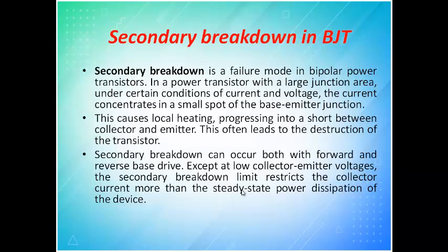That is what you have to remember. When you take a conductor, when it is in conduction, there won't be any opposition, whereas in a semiconductor there is opposition. This opposition will try to increase temperature. If this temperature increases, by nature semiconductors have a negative temperature coefficient, so an increase in temperature will decrease the resistance and increase the electron flow. This increase in electron flow is not because of potential. Because of potential, there is an increase in current flow that tries to break down the device, and that is primary breakdown.